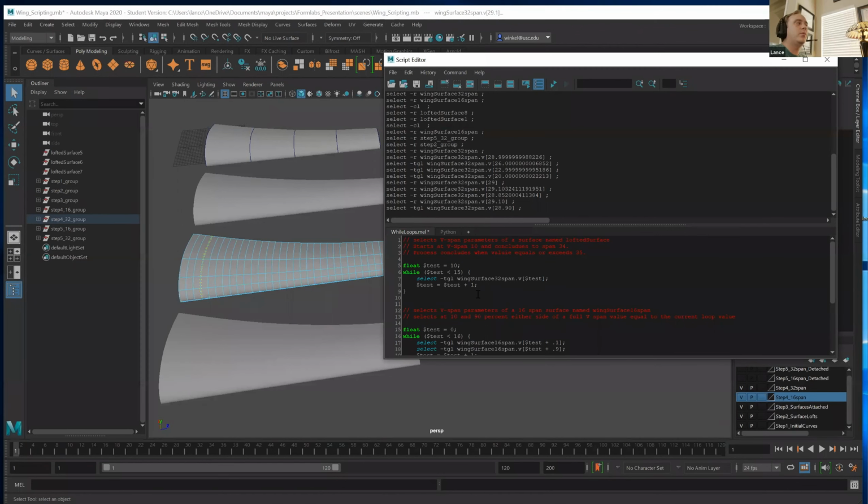Now, this is also a really important thing. If you've run Python scripts, you can cancel a broken script. In Maya, if you make a loop that does not close itself, you will literally create a memory error that you cannot escape out of. When you're writing scripts in Maya, save as often, but definitely before you start engaging a loop. Either start the loop knowing that it's good and then only add within that loop very carefully. But if you launch a mel script you can actually create a situation where it does not close itself and complete.